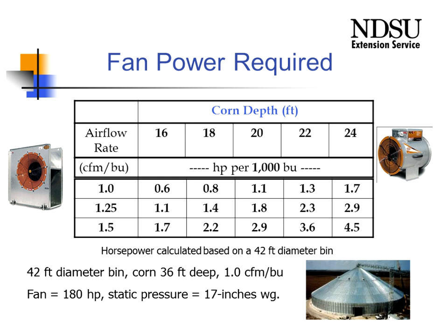At an 18-foot or just a little over 18 to 19-foot depth, that 1 horsepower per 1,000 works fine. But as we go up to a 20-foot depth, we're up to 1.1. A 22-foot depth is up to 1.3 horsepower per 1,000, and at a 24-foot depth we're up to 1.7.